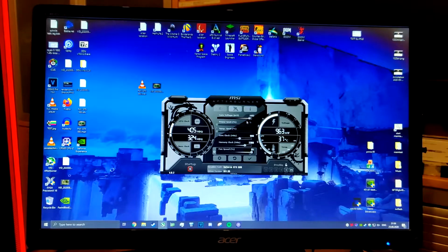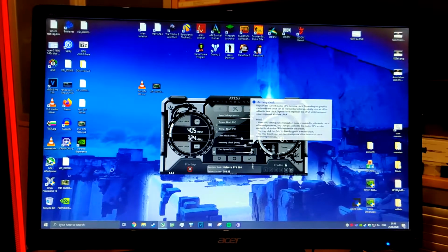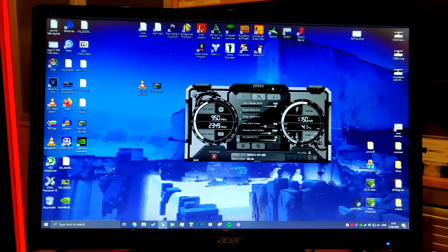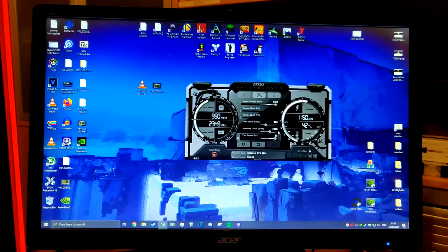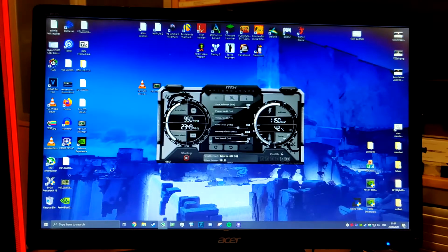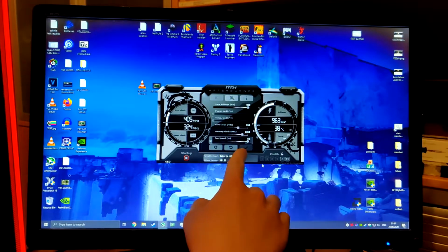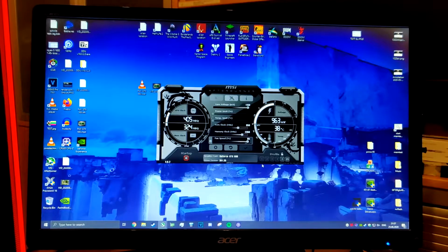So what we have here is we're going to max the fan speed. We are at a maximum for our voltage, and I know that this particular card can go to 950 megahertz and 2350, no, not 2320, oops, 2350 on memory. And you probably can hear the fan now, but for the sake of comparison, we're going to just leave it at static 85%. So that's the overclock for this card: 950 megahertz on the core and 2.35 gigahertz for the memory.